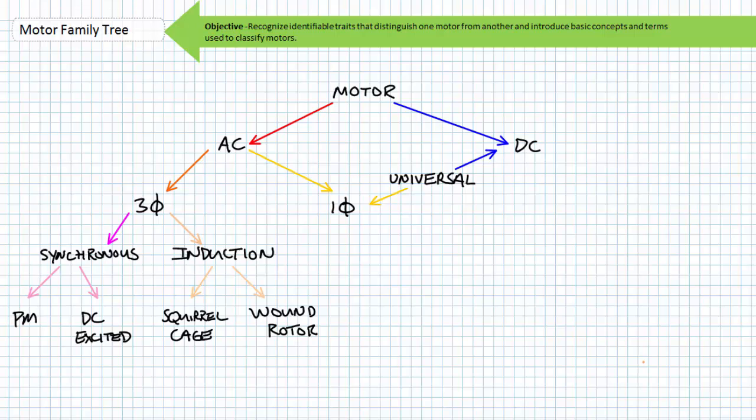If your three-phase AC motor does not have connections to the rotor, chances are it is a squirrel cage induction motor, where the rotor must necessarily revolve slower than synchronous speed for the induced electromagnets in the rotor to work. Loading this motor up slows it down. Unloading this motor speeds it up.